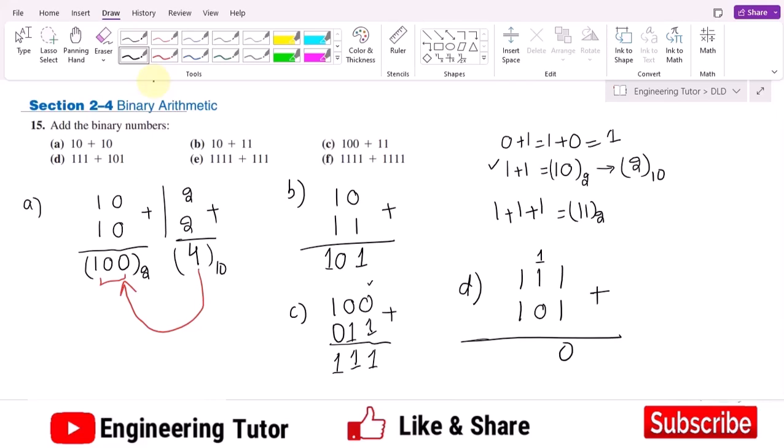Now I have to add 3 of them. So 1 plus 1 plus 0 is how much? Again this is 1 0, because this is now 2. So writing 0 here, and again 1 will be the carry bit. Now you can see there are three ones, and I have earlier told you that the summation of three bits is equivalent to 3 in decimal, which is 1 1. So writing 1 1 here, that is the summation of 1 1 1 and 1 0 1.